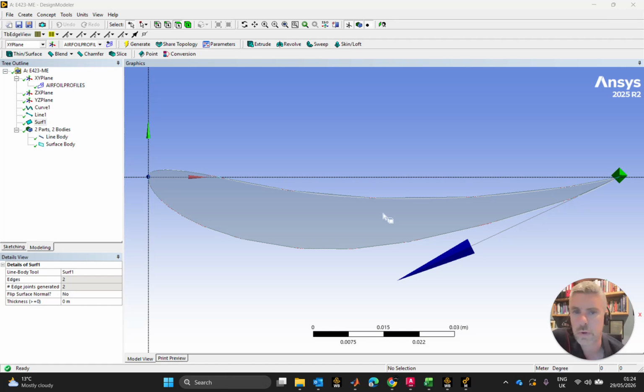The drag was going up by 10 orders of magnitude. You know, it was completely wrong. And I put that down to those singularities that were created through the very small increments on the angles of attack, and the resultant skewing of the meshed elements.